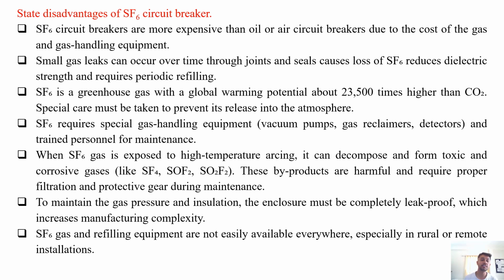SF6 is a greenhouse gas with a global warming potential about 23,500 times higher than carbon dioxide. So special care must be taken to prevent its release into the atmosphere. SF6 requires special gas handling equipment, that is vacuum pumps, gas reclaimers, detectors, and trained personnel for maintenance purposes.